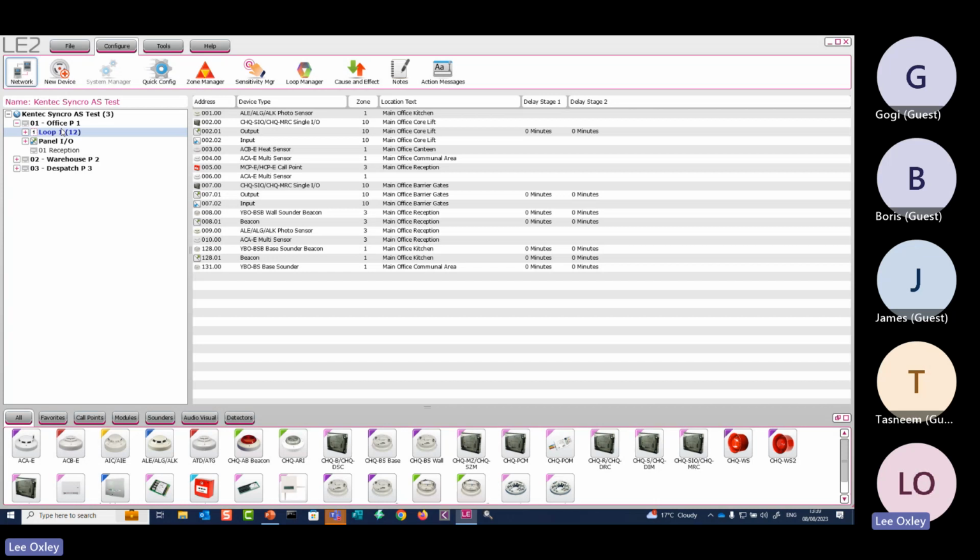Every time you add these devices, the panel's going to say unexpected smoke detector, unexpected call point, unexpected sounder, because it doesn't know about it, because you're physically adding these on. Again, what you're going to have to do is open the right enable switch, go to level 3 once you finish your installation, and then learn the panel. So it learns all these new devices you just added.